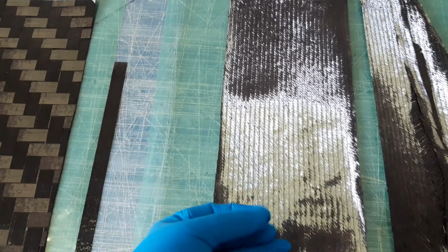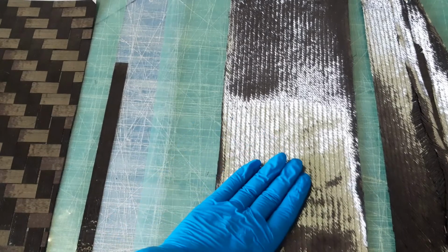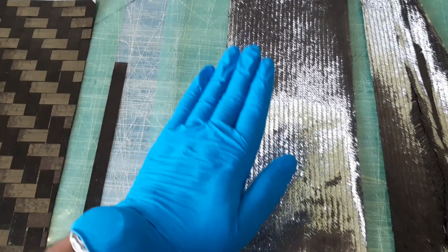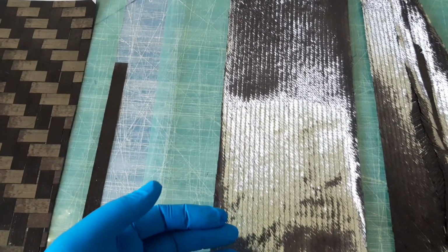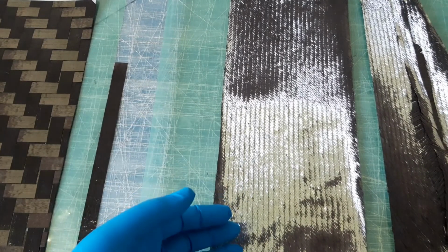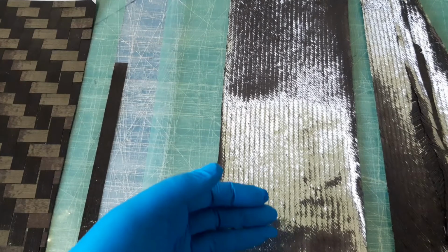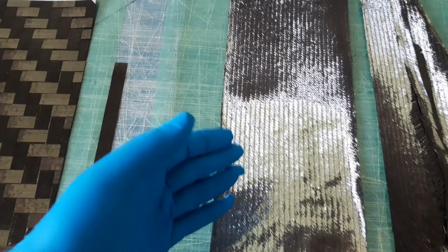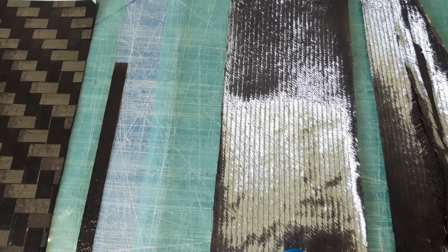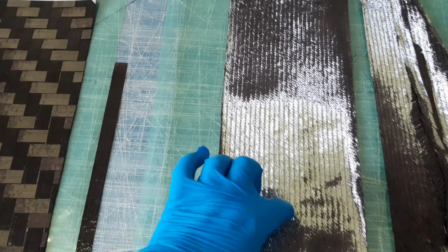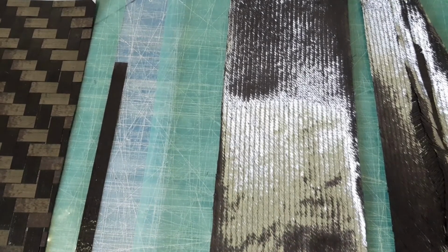One is to hold the fiber together, and it increases the toughness of this material if it is made and then laid up in composite material, and then you drop a ball on it to see the toughness of this material. This prevents the premature splitting of the fibers because of the through the thickness stitching that you see over here.